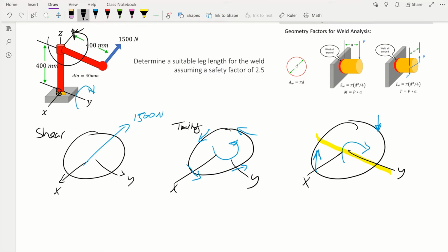And the reason is because as we push back, that tube wants to compress, right? But it's just running into that plate at the bottom. So the plate is helping support that tube, not so much the weld. Now, that's very different up in the front, right? Because as you're trying to put that load, it is trying to twist it towards the back, the front part wants to lift, right? And the glue that keeps it stuck together to the plate is that weld, right? So it's going to put it under tension.